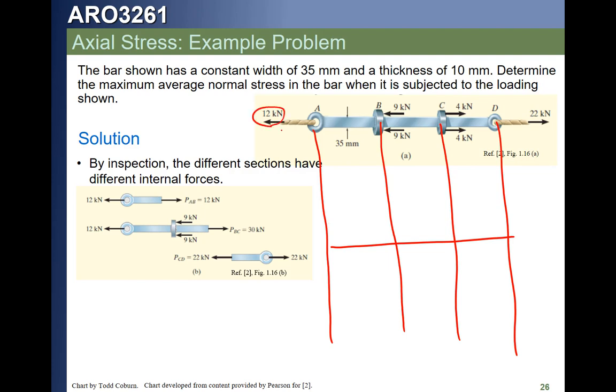So from point A, we have 12.00 kilonewtons in the part. Okay? And it doesn't change. Then you hit this point. At that point, we have 18 kilonewtons. Look, we got two nines, right? 18. So that makes it 30 kilonewtons, right? So we come up to 30 kilonewtons.